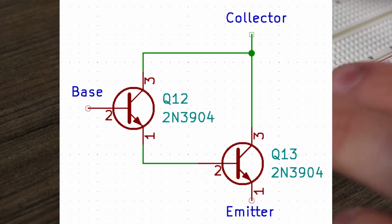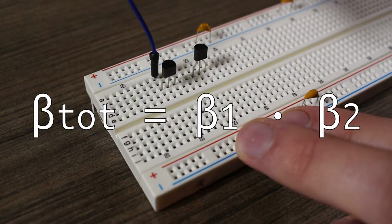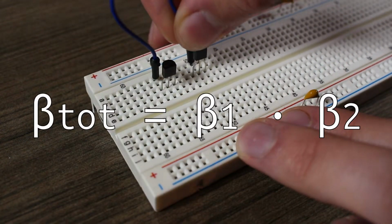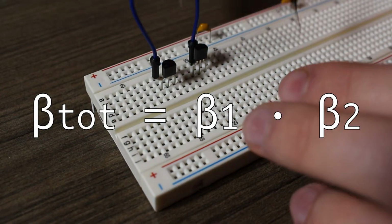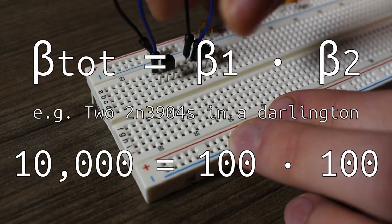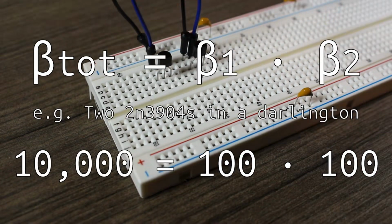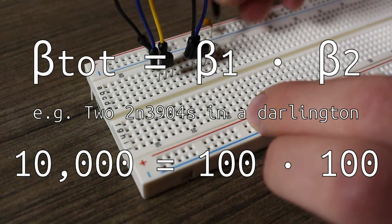In fact, we get a new overall current gain for this pair. The current gain of the Darlington pair is simply the product of the 2 that make it up. So, if we use 2 2N3904s and assume gains of 100 each, then we'd get a current gain of 10,000 from the initial signal. This means that we don't have to load down the input stage so much when driving the transistor, since we would need far less input current than a single transistor on its own.